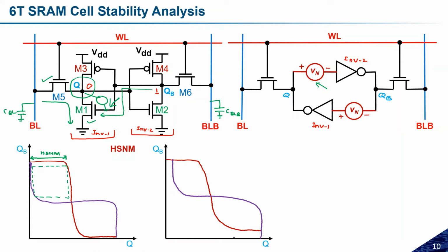You got the answer to what you asked? A little, sir. In hold operation, noise will not play any role? No, noise will play a role, but the important thing is that during the hold operation there is no involvement of these access transistors. These access transistors will be in off state, and if these two are in off state, they will simply act as an inverter.